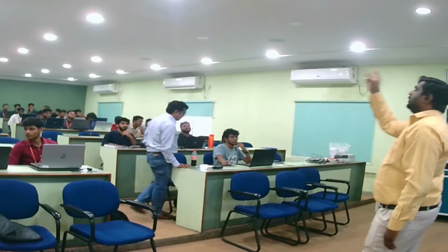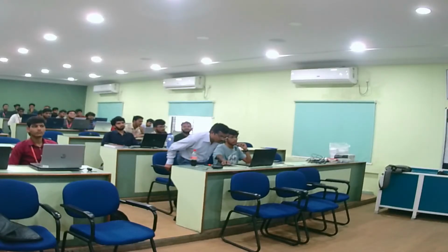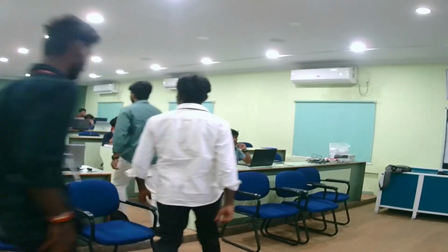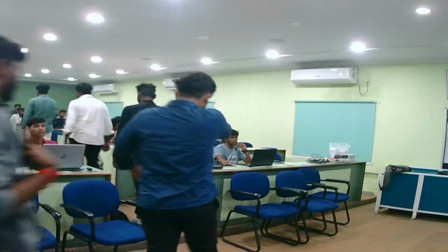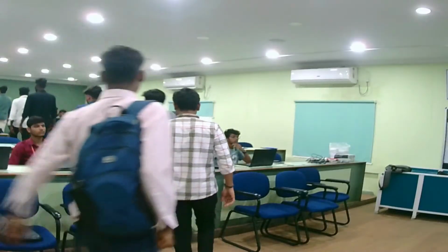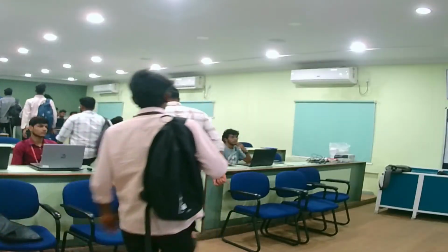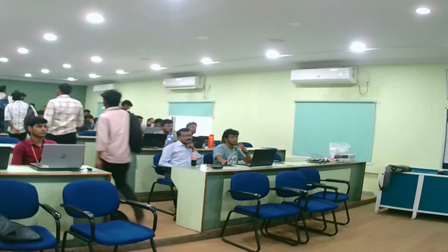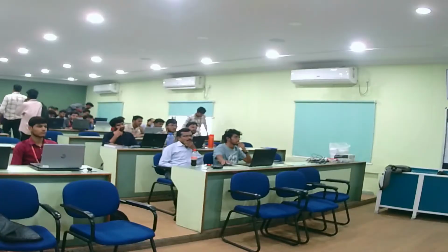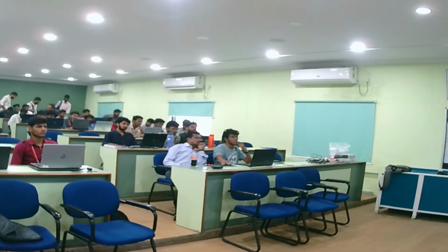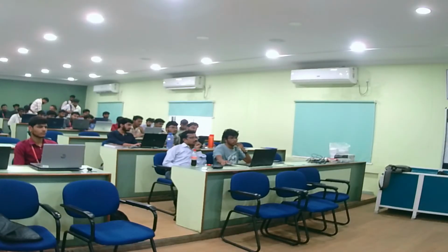I have which belong to numeric data type. Yes. So what I do here is I go to my program, I right click on my block diagram. Do you see how exactly in the front panel I have numeric, boolean, string? Here also I have numeric, boolean, string, and other comparisons. Different functions I have here.